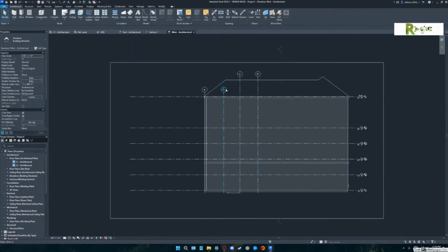Do you notice how C and D are up higher than A and B? Right. So it automatically sets to above the drawing. That's why you want to get your levels right first before you put your column lines in. Sort of like you want to draw your walls before you draw your floor. I got you. So the order is important.